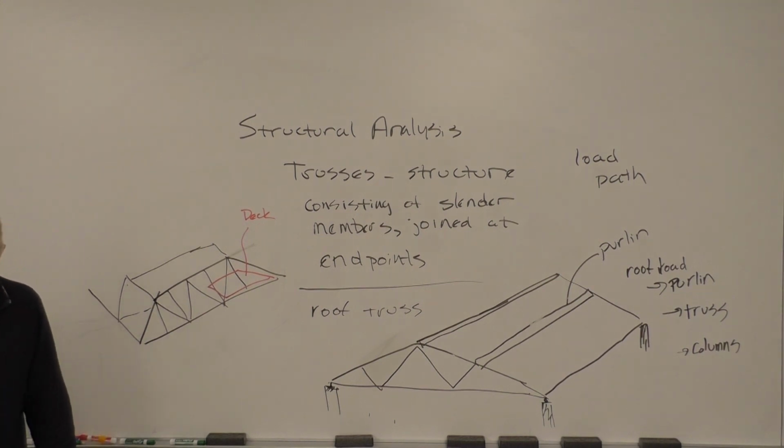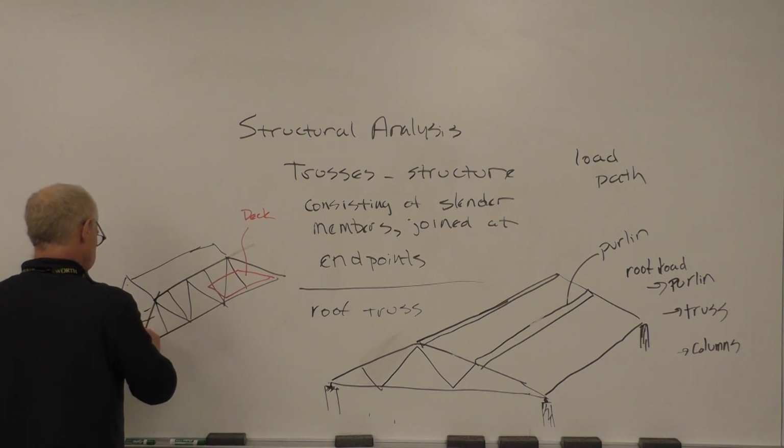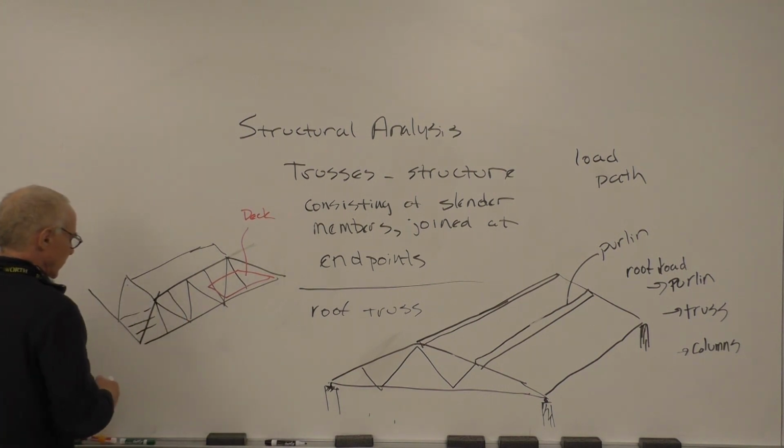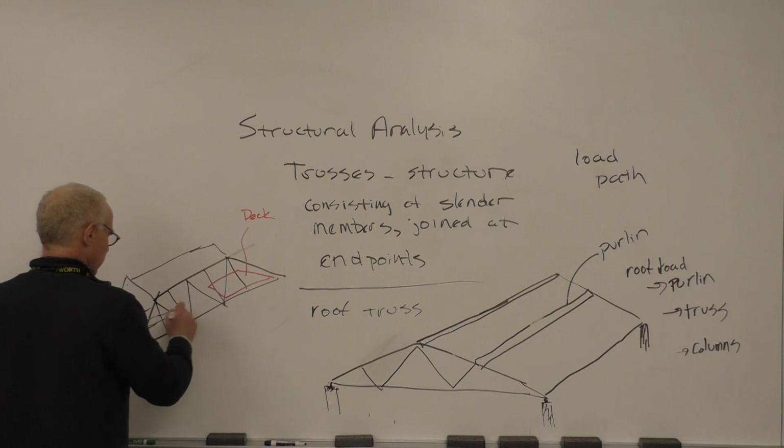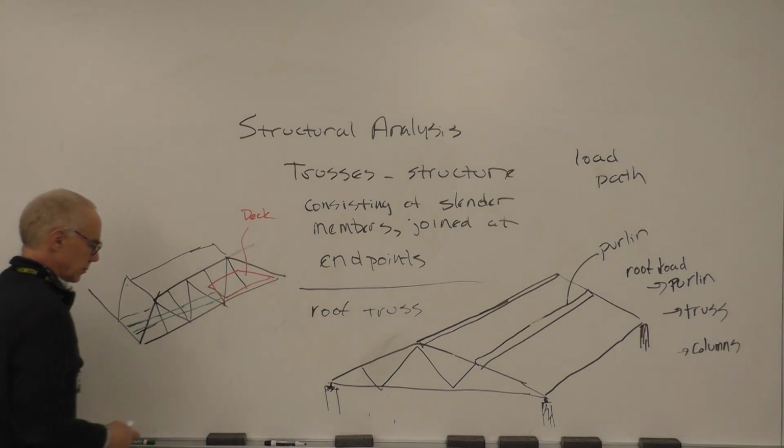And then we'll have what are called stringers, and those are going in this direction. Oh, now this is going to be a mess. Let me do this in green. So imagine these stringers are attached on the roadway. Basically, they're holding up the slab.